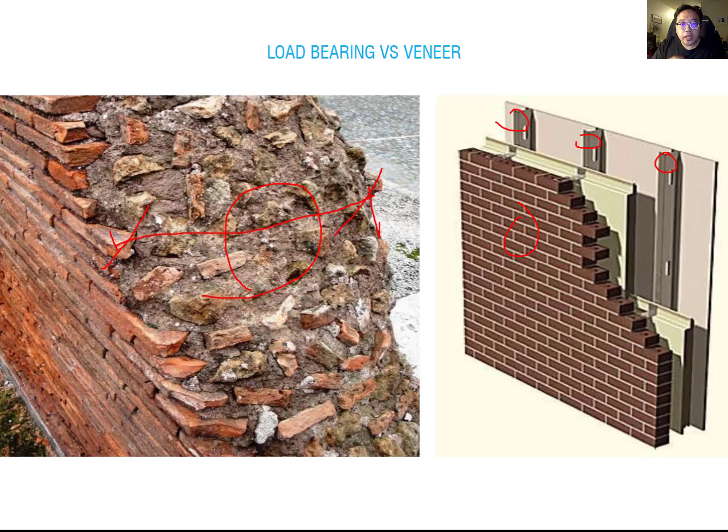So when you see this assemblage, this is the metal stud that works as the framing of the wall, which is the structure member, and then you can also see the interior finish wall, and you can see outside plywood sheeting, and you can add in the insulation. And then between the insulation you have to provide the cavity space, which is the air space. And then this brick wall is just held from the metal stud here. Okay. You don't worry about this assemblage right now. We talk about this assemblage next semester again.